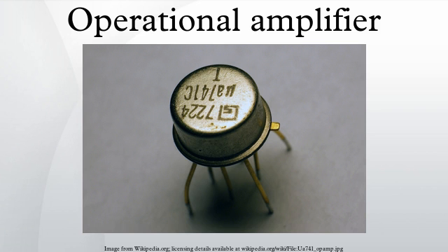Classification. Op-amps may be classified by their construction: discrete, IC (most common), hybrid. IC op-amps may be classified in many ways, including military, industrial, or commercial grade. This may define operating temperature ranges and other environmental or quality factors. Classification by package type may also affect environmental hardiness, as well as manufacturing options. DIP and other through-hole packages are tending to be replaced by surface mount devices.